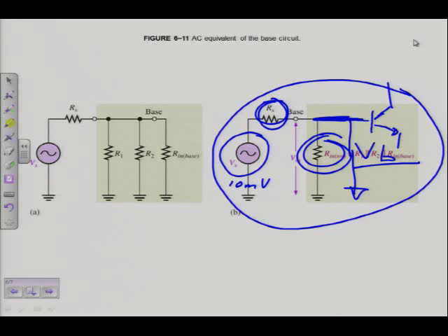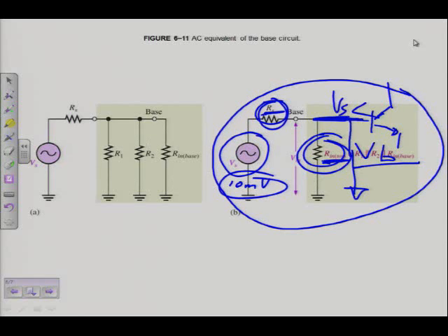So if I know that's the voltage, then that resistance is on top of the line: R in total divided by total resistance, which is RS plus R in total. That is the ratio for the voltage divider times Vs, which in this case would be the 10 millivolts. And then I will find a voltage at the base less than Vs, because it has been divided by the voltage divider.